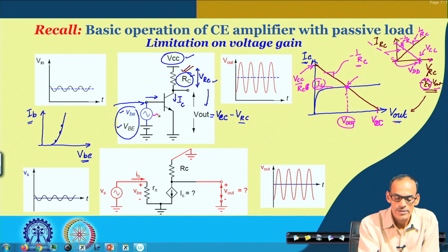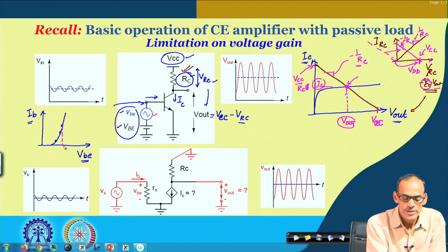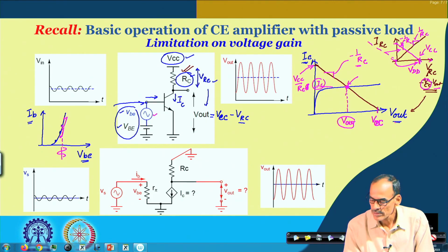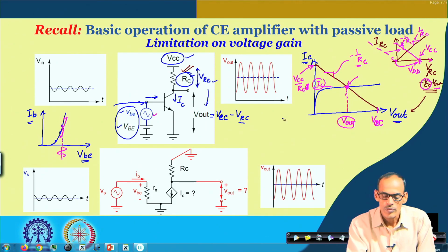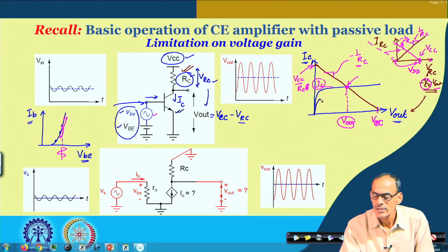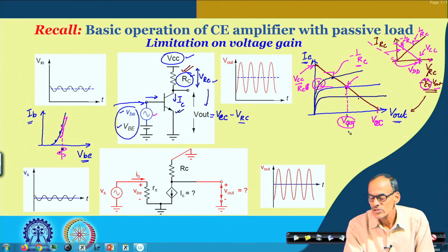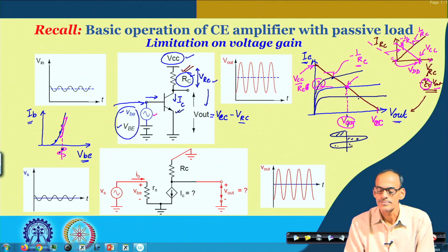Now, whenever we give a signal, as you may recall, with respect to a DC operating point, it means we are changing the device characteristic up and down with respect to its exponential relationship. That makes the device characteristic, which we call the pull-down element characteristic, go down or up. As a result, since the operating point is changing by varying this voltage, it is also changing Vout, the output voltage, and that is how we get the output signal.